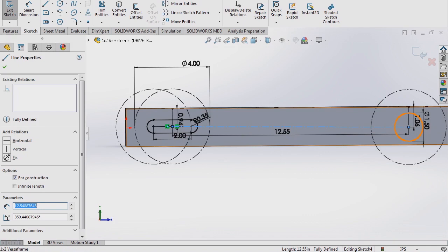Remember, it's like a 16th lower. Also, this is a little bit higher, so it's maybe like an 8th, I think. Anyways, they're not on the same level, so I just want to make sure the sprocket center to center distance is correct. Otherwise, it'd be going from where it would be level.